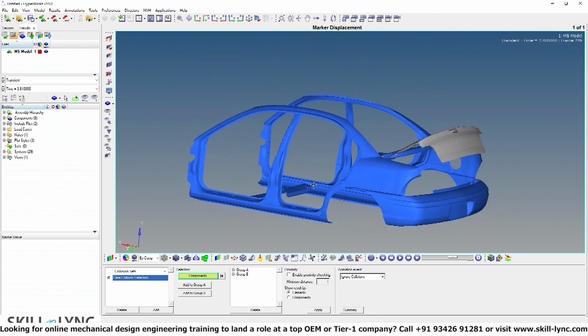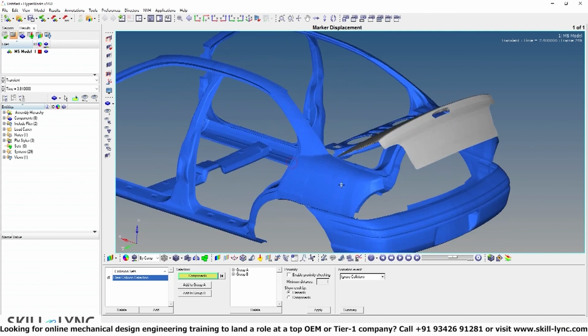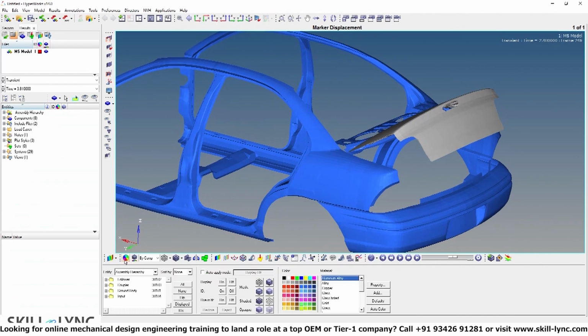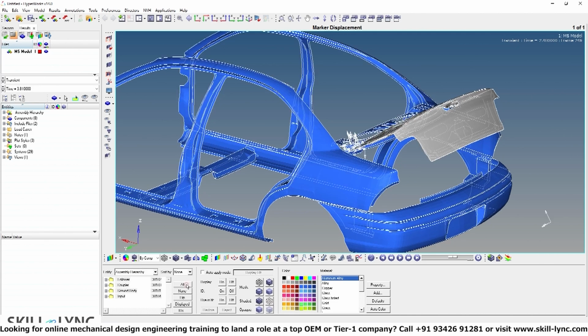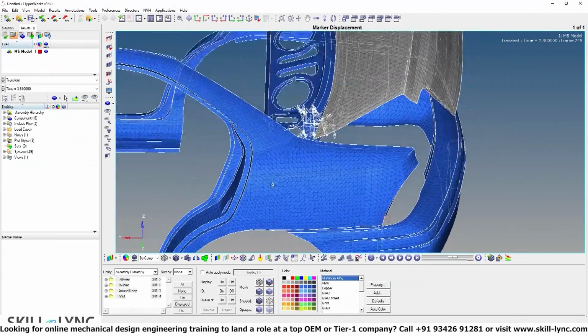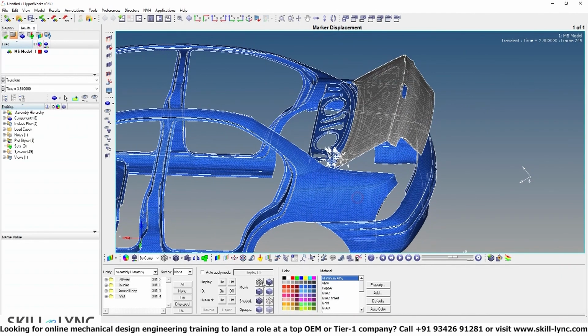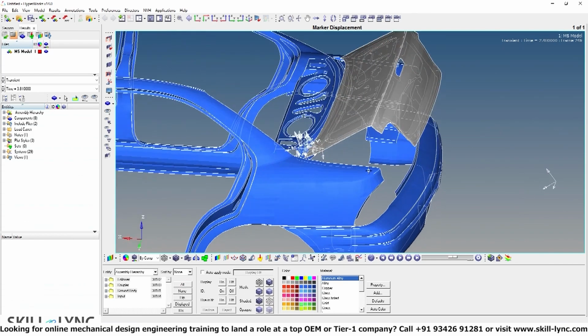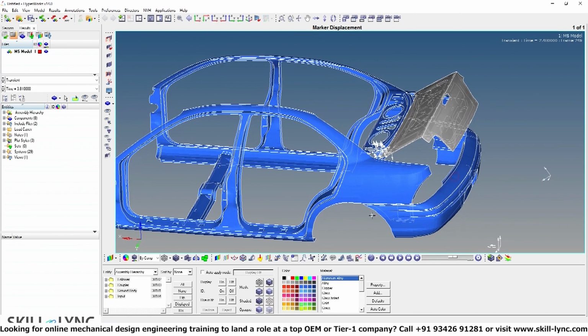Before going to that, I want to show you one thing. You don't see any mesh on the screen, but actually it is meshed. To visualize that, you can go to this particular option, which is the graphics option, and say all. So it selects the entire thing, and click on this. This is the automatic meshing. It's done, but this is how you visualize it. Usually it will be switched off. So you select everything, say all, this option here. So you can't see the mesh. If you want to visualize it, then you have to click this particular option.